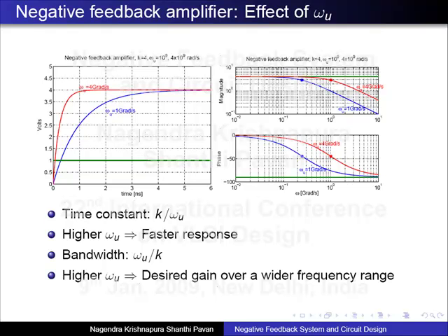No, there is no tweaking here. It is omega u that is doing the tweaking, right? There is no other tweaking. If you think about it, your acceleration and deceleration, that is done by this integrator, which is omega u. It is like you are doing it faster or slower. Now we have assumed that there is no other delay in the system. If there are other delays in the system, things might get complicated. But right now what is doing the tweaking is this block, which has a parameter omega u, which is basically related to the speed at which you tweak.